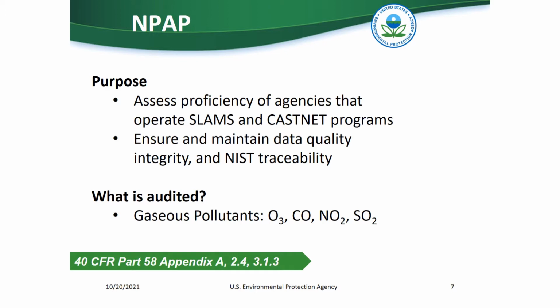EPA's contractor ESAT conducts these assessments for sites that monitor gaseous pollutants, which include trace gas level NPAP at NCore and NPS CASNet sites. During these audits, a contractor will generate pollutant concentrations from a NIST traceable standard to the contractor and organization's instrument to compare results. Contractors may also perform ozone loss line tests, instrument certifications, gas certifications, and audit system comparisons with another regional system.